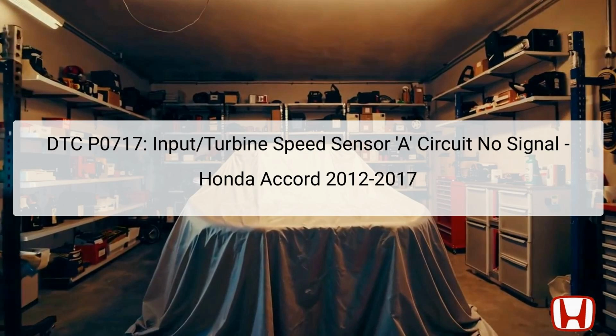This sensor is located in the transmission area, typically mounted near the torque converter inside the transmission housing. The error code suggests an electrical circuit malfunction, which could be caused by issues such as open circuits, shorts, or poor connections, but it cannot be caused by mechanical problems within the transmission itself. Proper diagnosis involves reviewing freeze frame data, onboard snapshots, and following a systematic troubleshooting approach to identify the faulty circuit